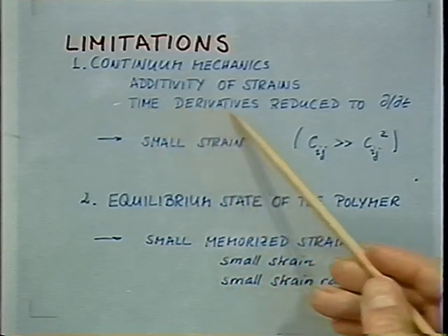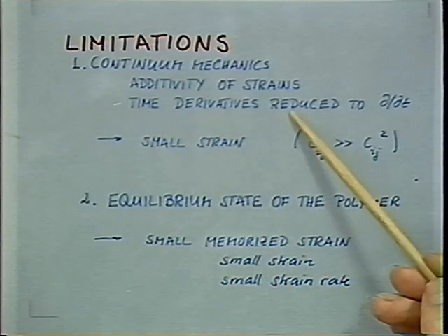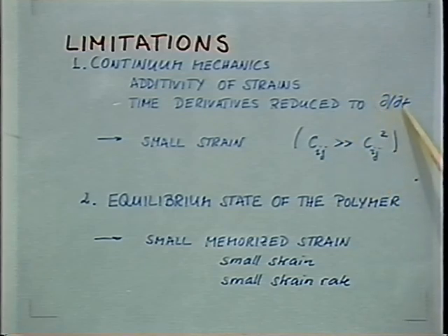In case of differential models, which we haven't discussed much, the time derivatives are plain partial derivatives at small strains, but you have to go to the co-rotational derivatives, Zaremba, Fromm, and those people last century, or in 1950, Oldroyd, who derived time derivatives to accommodate large deformations in a co-deforming coordinate system. So we would have to accommodate for that if we go to larger strains.